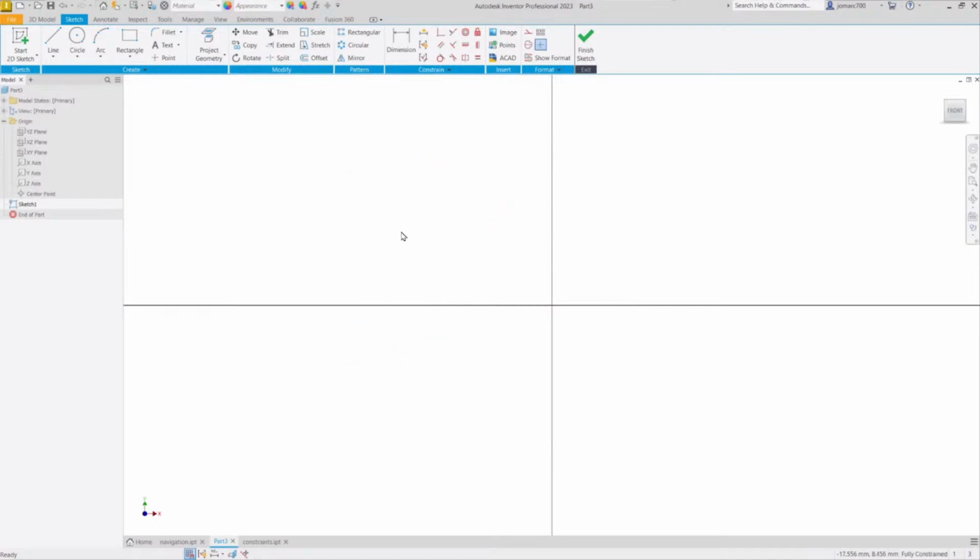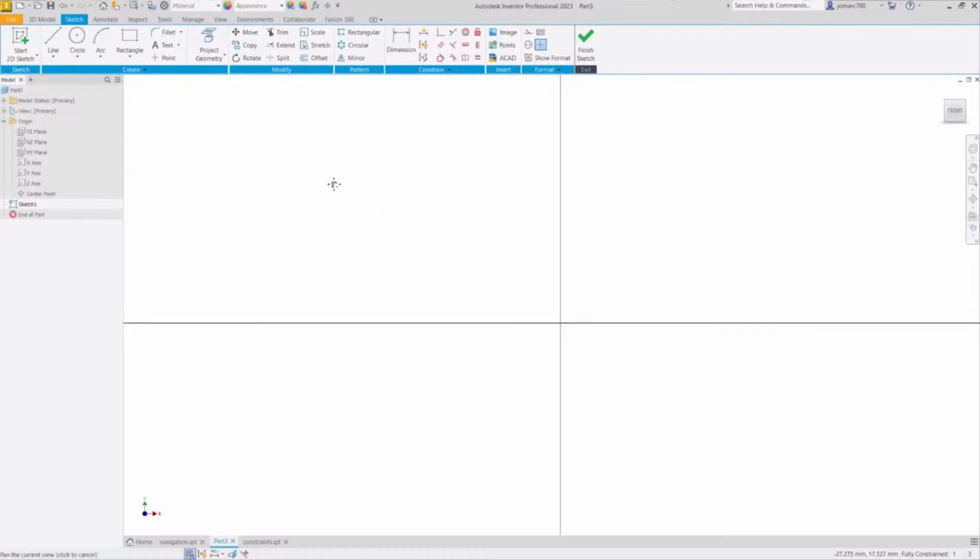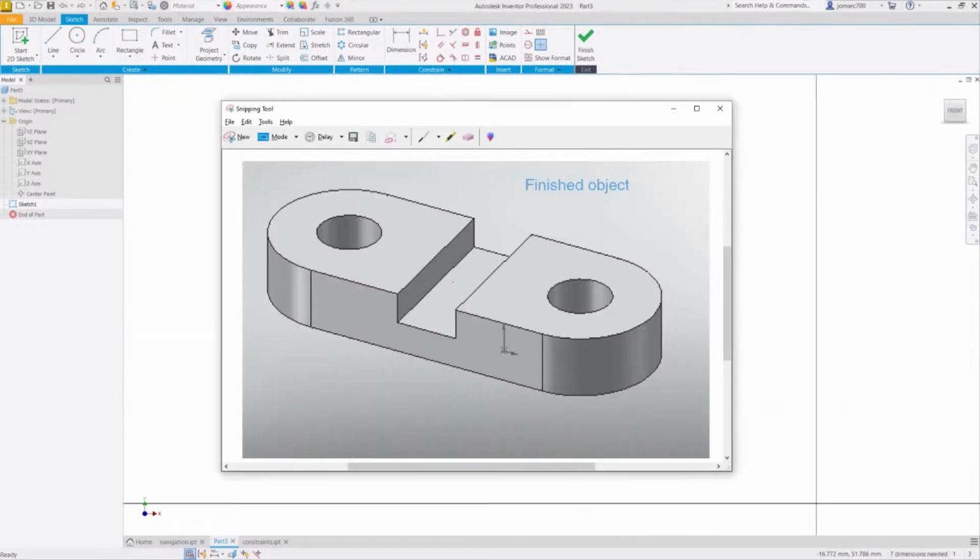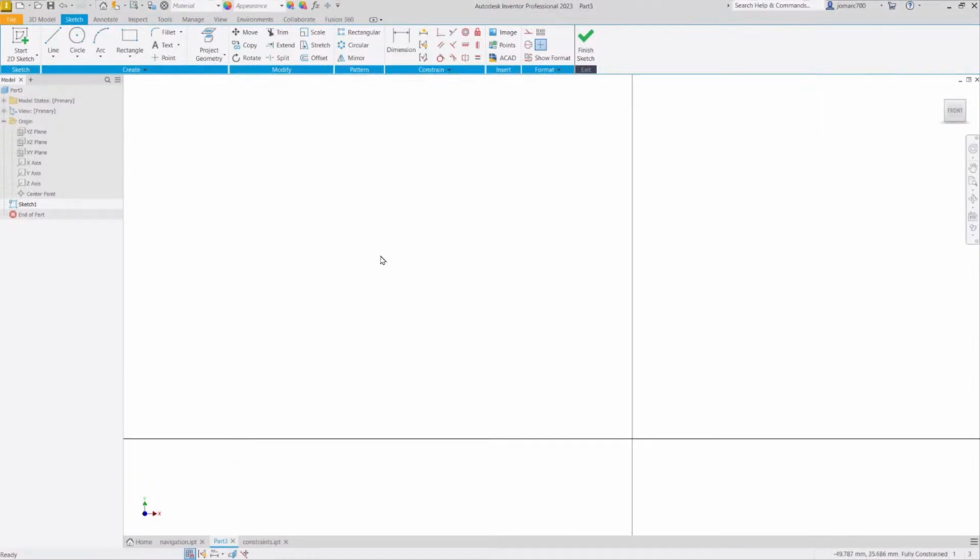From here, highly requesting that you follow along, I'm going to pan over here. Our intent is to quickly recreate this 3D object. Let's start by utilizing the line command. Heading up under create, selecting line. Let's draw a line. Left click here. Left click, left click, left click, and move to the end of this other line, and a double left click to end the chain of lines.